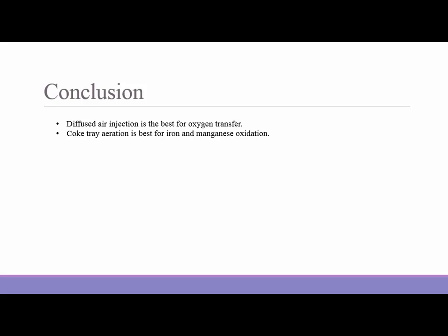And I conclude by saying that diffused air injection is the best for oxygen transfer, whereas cascade injection aeration is the best for iron and manganese oxidation. Thank you.